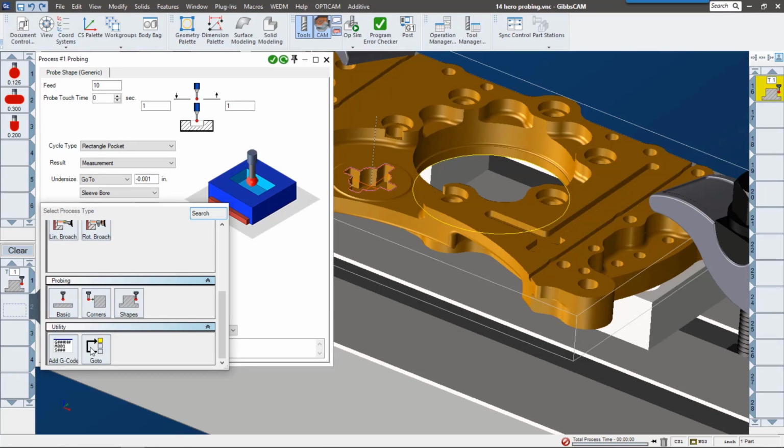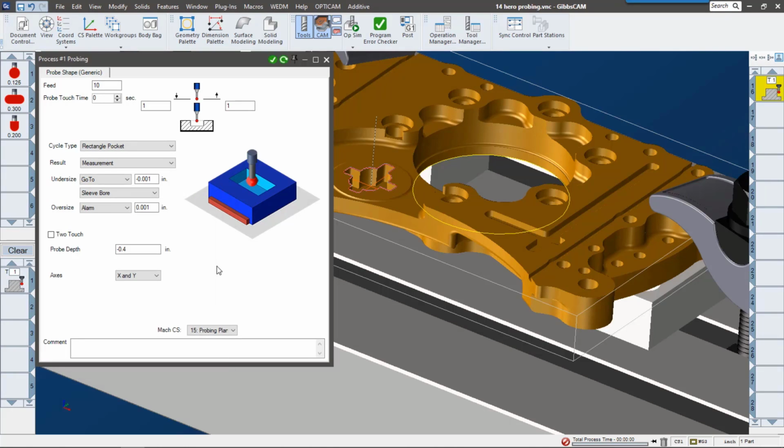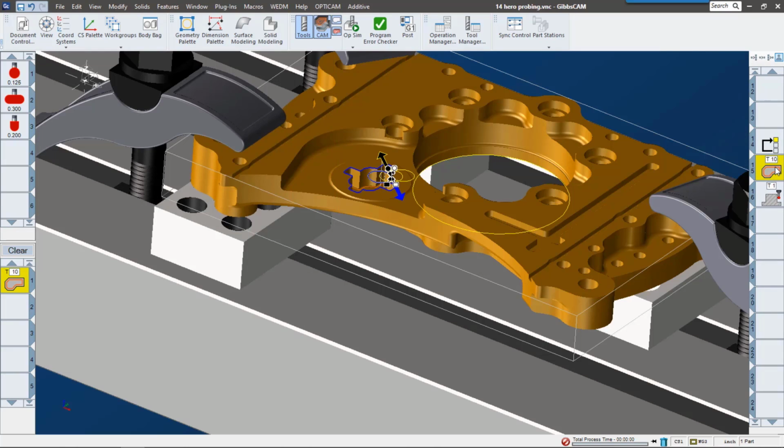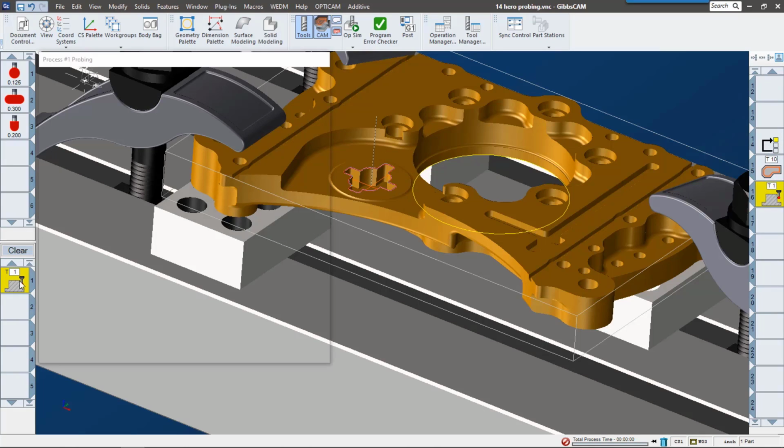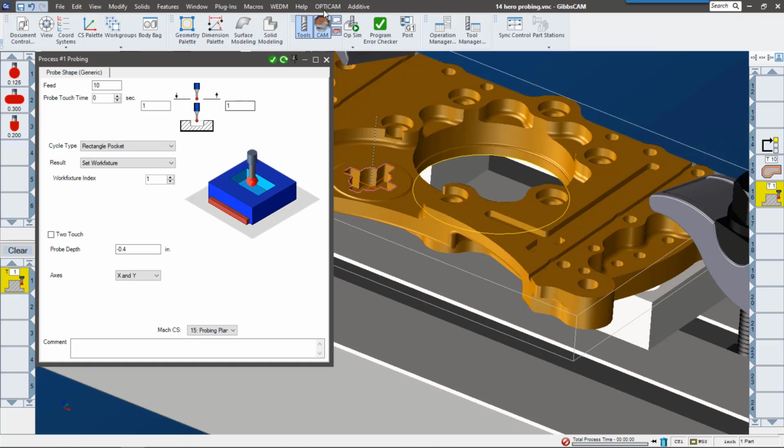We can just insert it by pressing here. It's down at the bottom. And what these are is they're targets. And I've kind of pre-baked this a little bit. If we look over on the right, you can see I have a GoToMove, and then there's my contour. So I'm going to say go to the sleeve bore. Again, here's my target, and then run the program from there. Let's go ahead and check this out in simulation.